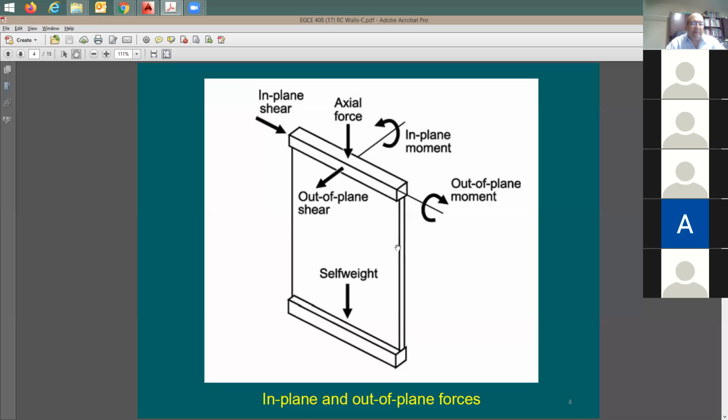But in here, the wall is going to be a long wall. Maybe the length is 50 feet and the thickness maybe 18 inch and the height maybe 14 feet or so. So this weight should not be ignored. You really need to figure it out when you're doing your analysis.